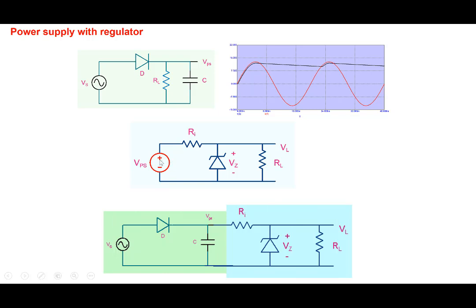Okay, so we took this out, we put this circuit here, and this load resistor is after the Zener diode. The load resistor is over here. Okay, and RI is as it is, and so this is the circuit that we obtain here. The idea is that with this particular circuit, we would be able to obtain a much better DC voltage with much reduced ripple voltage here. Okay, so a properly designed circuit would then give a superior performance compared to a simple power supply circuit of this kind here.